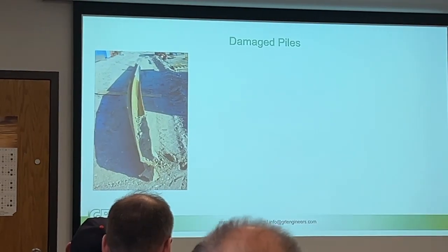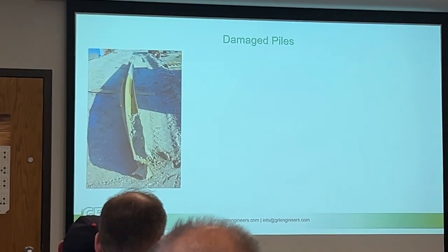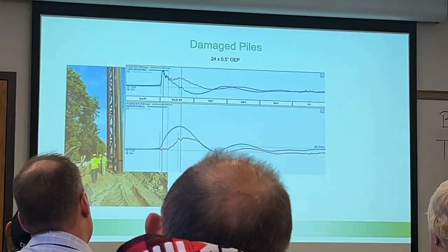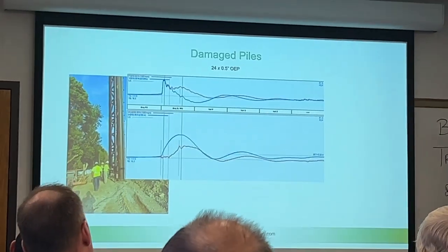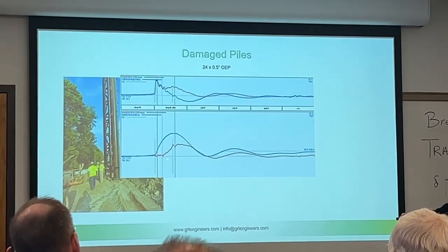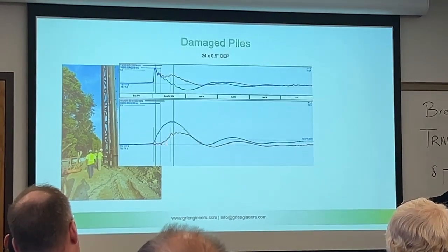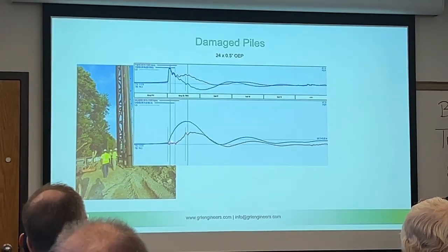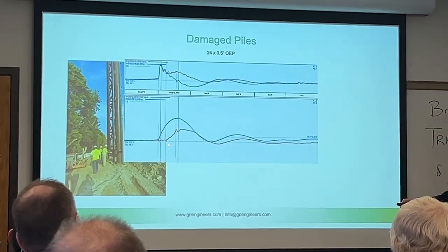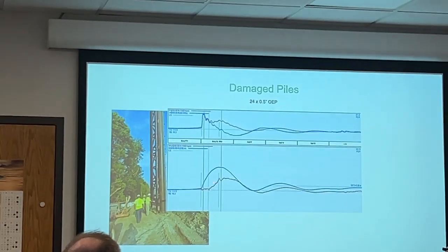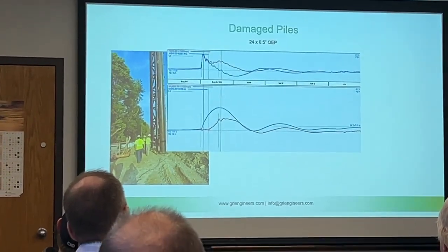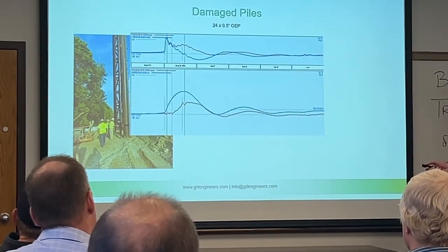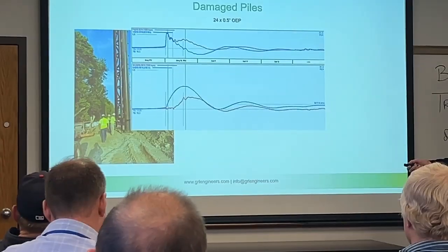But you weren't changing the impedance, or were you? No, we're not changing that, right? So we are driving one of these piles, and you can already see there's not a beta marker here. This is a splice that we put in the PDA, right? So we were already suspicious of this occurring, so we've got a marker exactly where the splice is. Within the PDA, you can mark where any splice is, so you can keep your eye on those questionable locations. And I think there's another splice shallower as well.